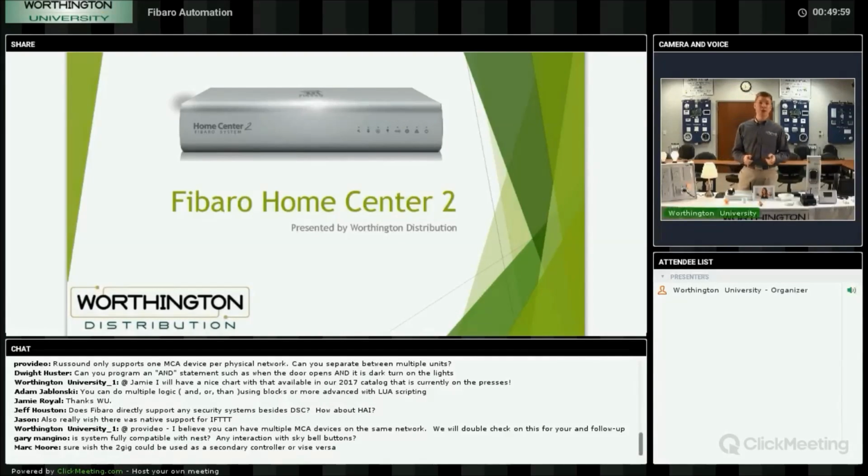At the moment, the only security system plugin that we're aware of, and we've looked through it fairly recently, is the DSC. We have a slide on that, but I'll go through it briefly. It's really pretty easy on that DSC system. You're going to use the IT100 module, which is the serial to keypad bus interface. Because it sits on the keypad bus, it knows everything that's going on in the system. It can arm and disarm. It can show you the status of every single zone. It can even bypass zones. So everything you can do from a keypad, you can do from this module.